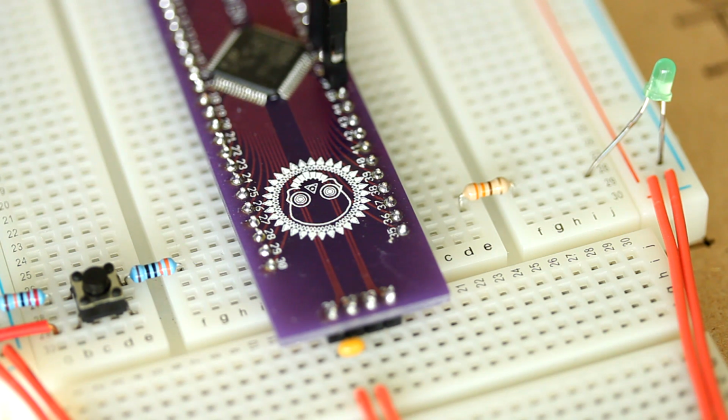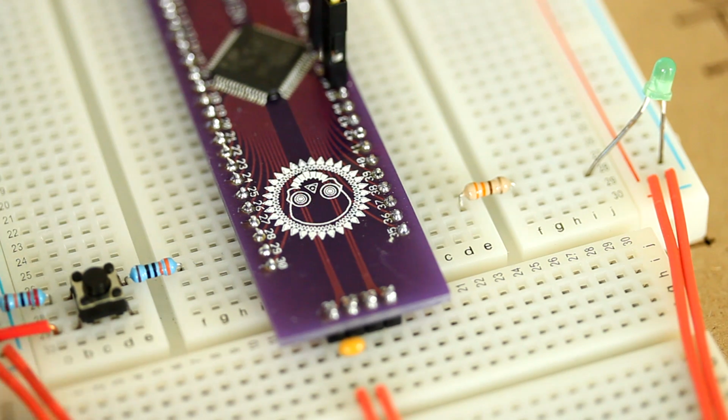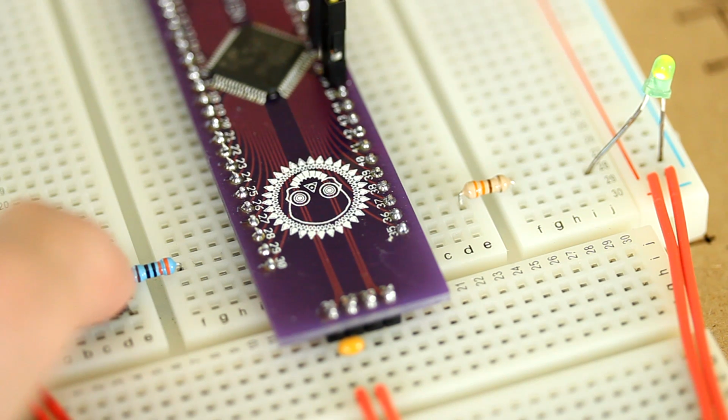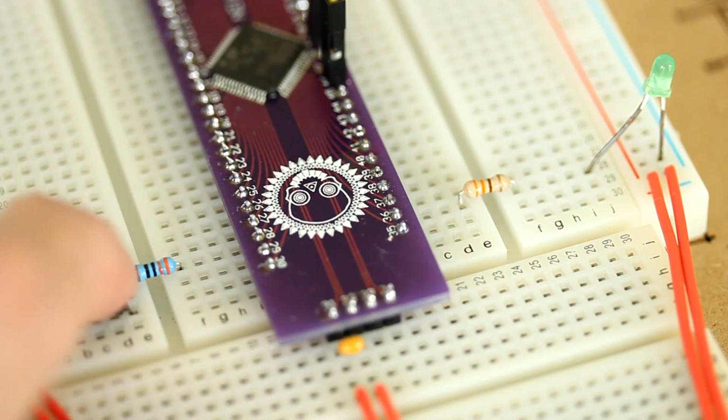Okay, the microcontroller was programmed. When we press the push button on port B pin 1, you'll see that the LED lights up. So in review, we've set up the LED for output, we've set up the port B pin 1 for input, we installed a push button switch, and we created code to make the port B pin 1 be read by software, turning on the LED and turning off the LED.